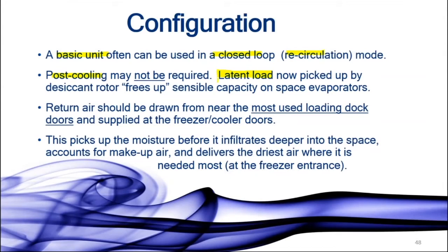Why? Because, and here's a point we'll come back to several times now, we are going to put the latent load on the desiccant unit. All the water work that was done by those space evaporators is going to move to the desiccant.